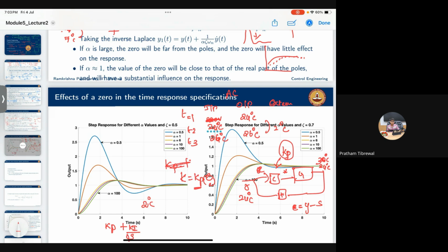That is, it is integrating the value of error over a period of time. At first, it will integrate 0 plus 2. Right now it is considering it as 2, so it will generate some value that is proportional to it, to reduce the 2 degrees Celsius that it increased.